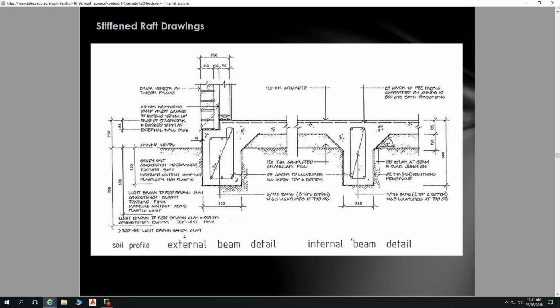Sometimes we want a lot of slumping concrete. Sometimes we want that concrete to go like this, when we've got to get it into some tricky formwork, and various precast stairs or cast on site stairs, all this sort of thing, where you've got to get it to form into these scenarios. So yes, there is definitely a relationship between slump and strength. Typically your less workable concrete is higher strength.